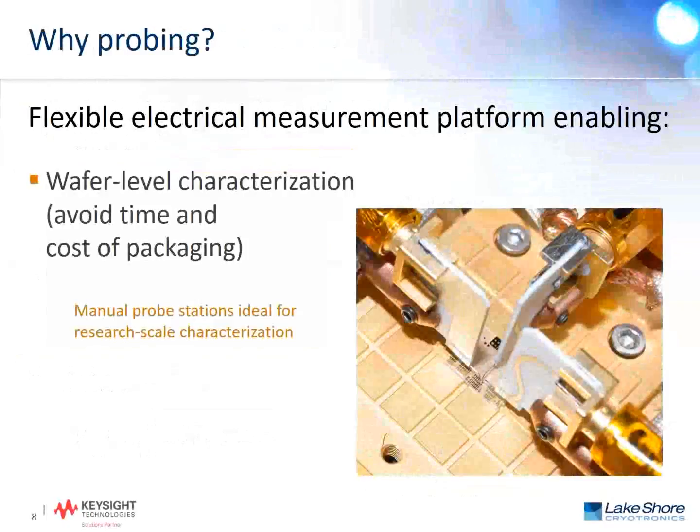So now that we have this flavor for doing variable temperature transport property measurements, we move on to our second question, which is why probing? Probe stations basically offer a flexible electrical measurement platform that first offers wafer level characterization. By probing or measuring the device at the wafer level, we avoid the time and cost of doing the packaging.